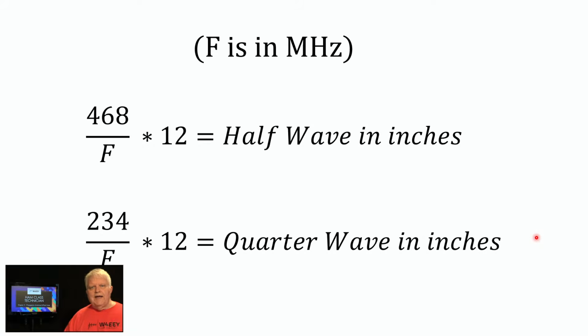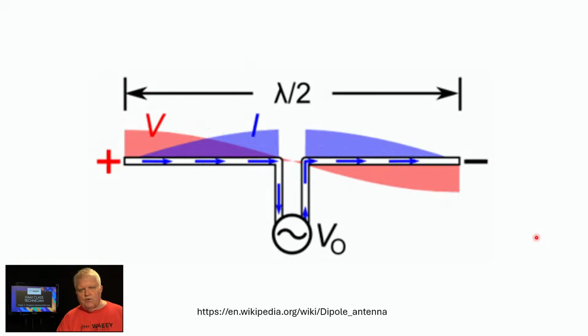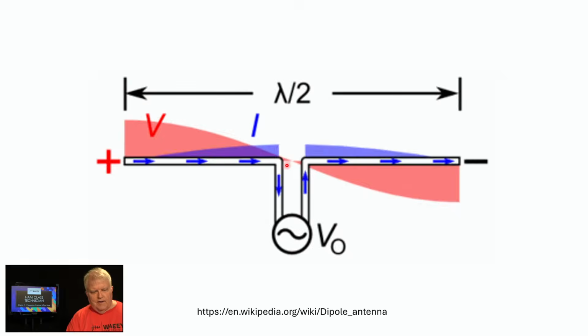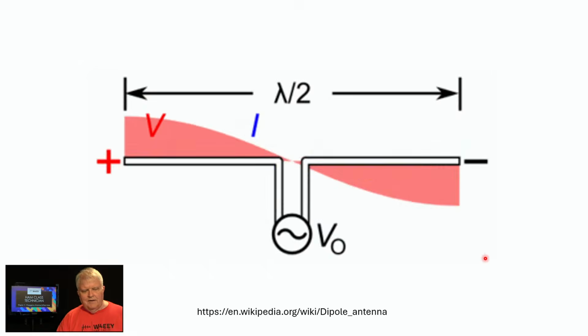And when we're looking at a dipole antenna and we're looking at voltage and current distribution on that antenna, that's what this is all about. The high current point of a dipole antenna is at its center. That's what the blue represents. You see the current minimum, maximum and minimum? And the high voltage points of a dipole antenna are at the ends of the antenna. That's what the V is representing. High voltage here and high voltage out here. So this is a normal phenomenon.